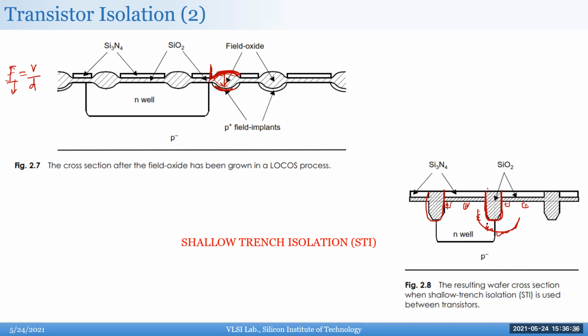And this shallow trench, most of the processes, especially in analog, when you use 130 nanometer, 65, 90, 180, any of these, they're all mostly shallow trench isolated processes. And this does give you some extra problems. Mostly, they put a lot of stress on the devices right next to it, and they change the parameters of those devices.